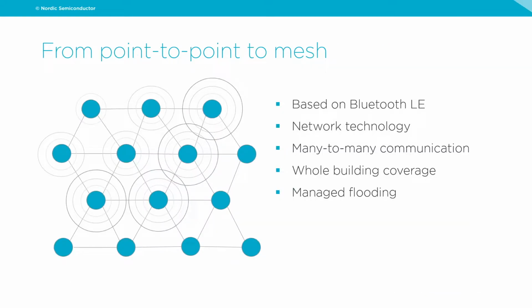So what does this look like from point-to-point to mesh? It's based on Bluetooth LE and only LE. It's a network technology that allows many-to-many communication, and the goal is to cover whole buildings, and it does so by managed flooding.